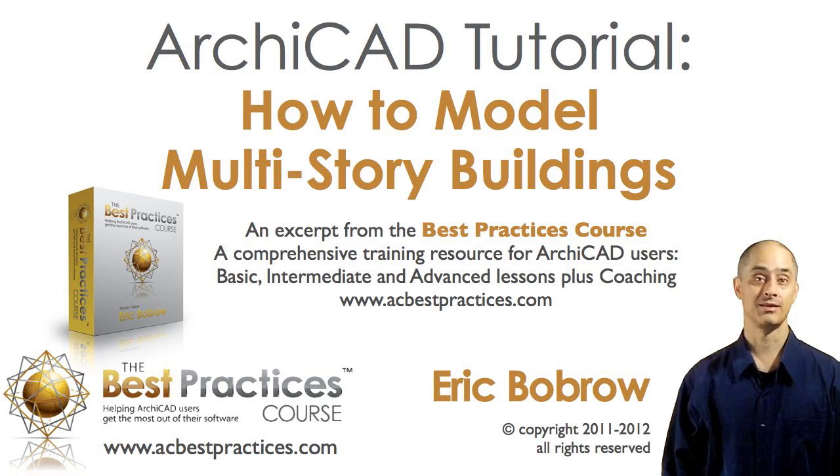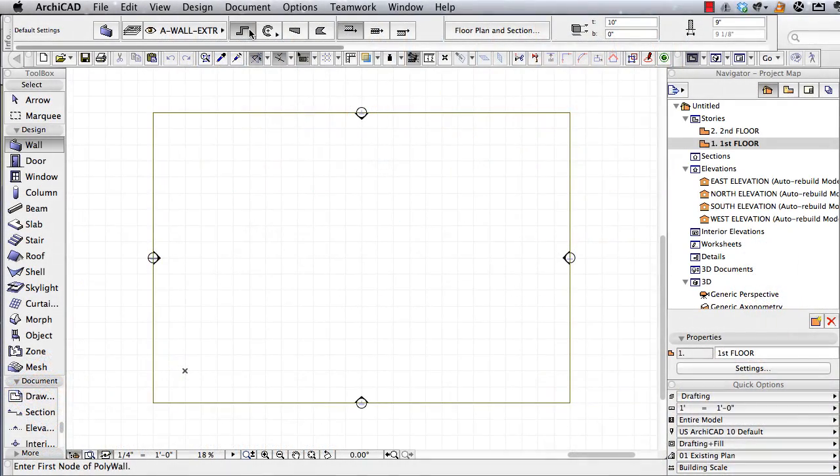In this ArchiCAD video tutorial, we'll look at how you can create a multiple-story building in a variety of different ways, starting from a very simple conceptual model and getting all the way up to a detailed model that gives you very clean sections and elevations directly from the model. So we'll start out by drawing just a box of walls here.